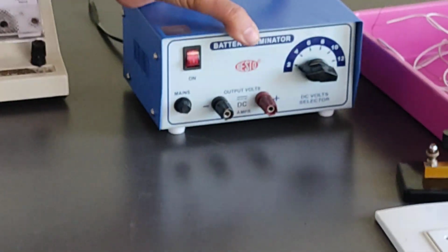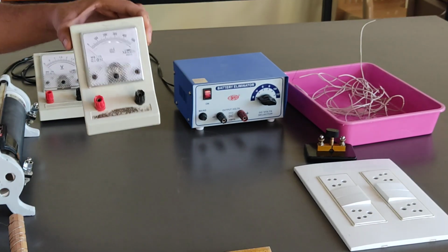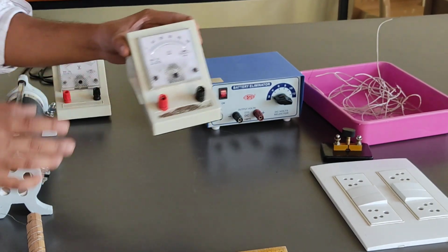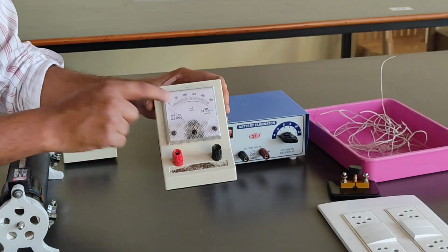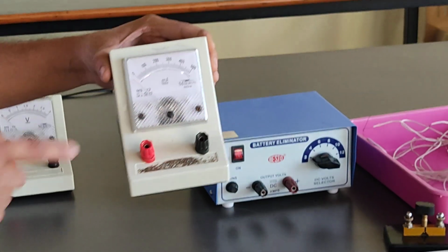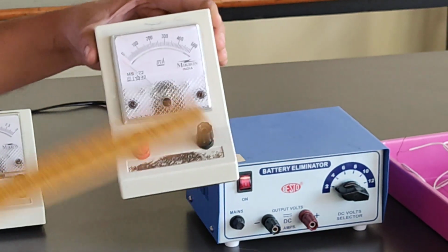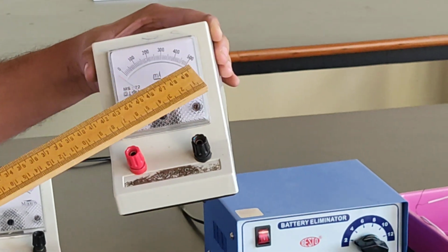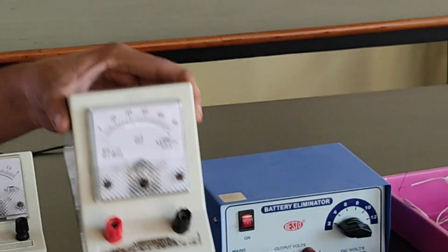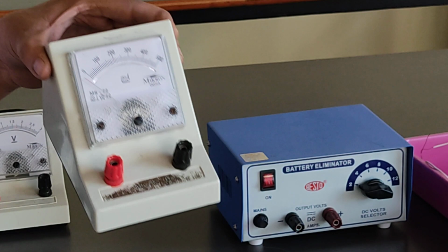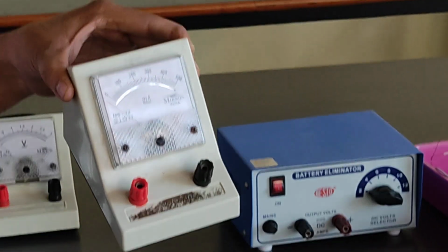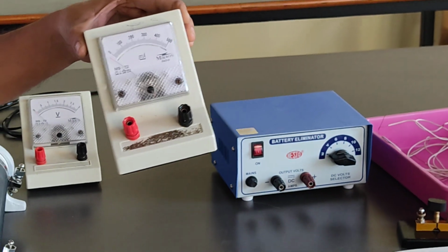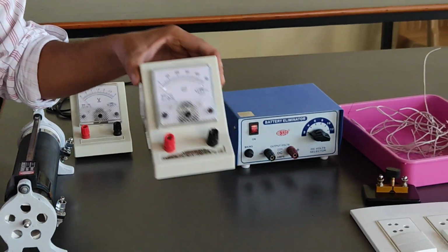This is your battery. Then we have here an ammeter. Here I have chosen a milliammeter, means in our circuit diagram the current is very small, so I am using what? A very low range ammeter, that is what? Milliammeter. You might have seen here mA, m indicates milliampere. So the range of this milliammeter is 0 to 500 milliampere. So whenever you are using a milliammeter in a circuit, make sure that you are using it in series. So the ammeter should always be connected in series. This is your ammeter to measure the electric current I.